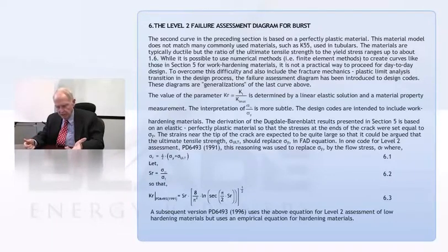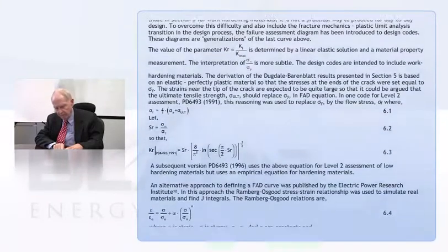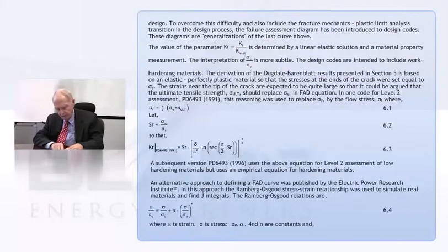It's called the Ramberg-Osgood stress-strain equation. And if you look at that equation, you have epsilon over a reference strain. I'll tell you what that is later. And then you have the stress over a reference stress. And then you have the ratio of the stress to the reference stress to the n. N is going to be a big number. It goes up to about 20 on some materials. And that just goes up and takes off at your yield point.